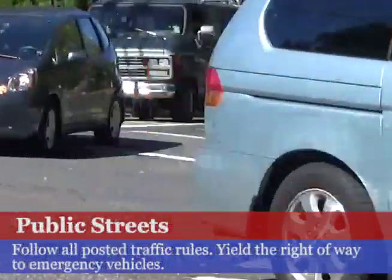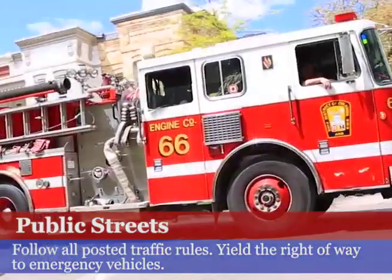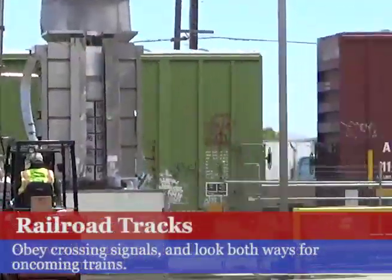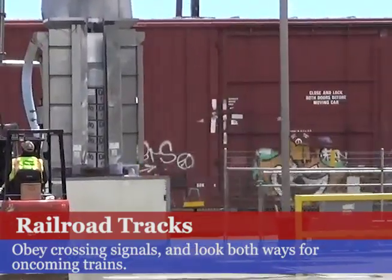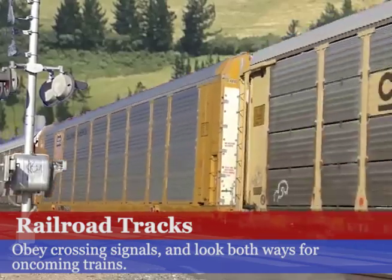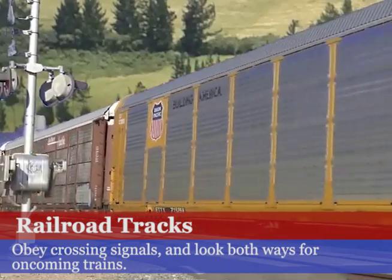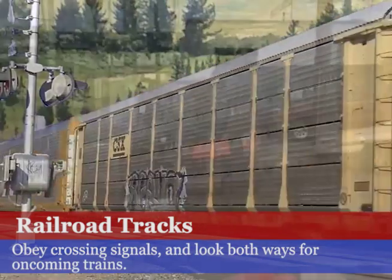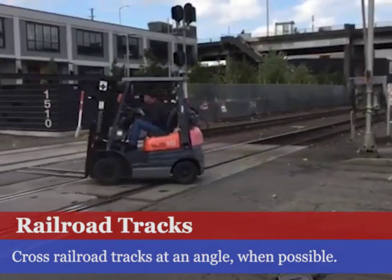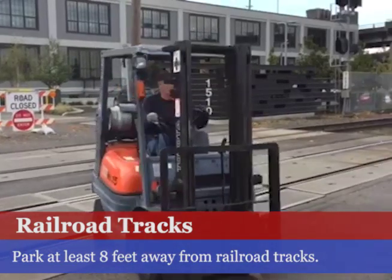When traveling on public roads, always follow posted traffic rules and speed limits. Yield the right of way for emergency vehicles. Crossing railroad tracks on forklifts requires special precautions. Obey the crossing signals, but do not rely on them to alert you of approaching trains. They often only provide a 20-second warning, which may not be enough time to clear the tracks. Stop and look both ways when approaching the tracks. Cross the railroad tracks at an angle, if possible. Never park within 8 feet of railroad tracks.